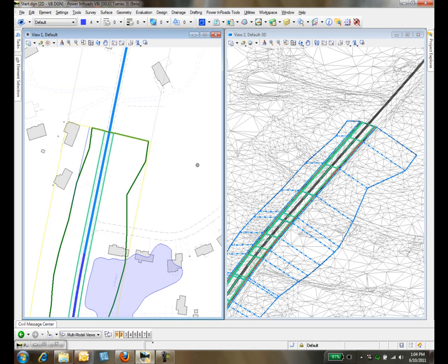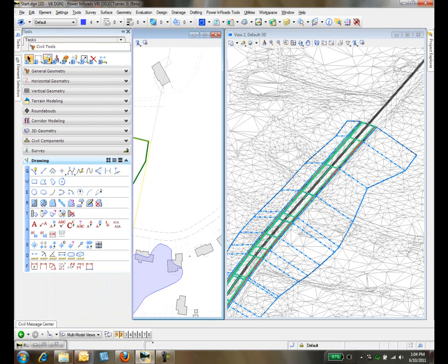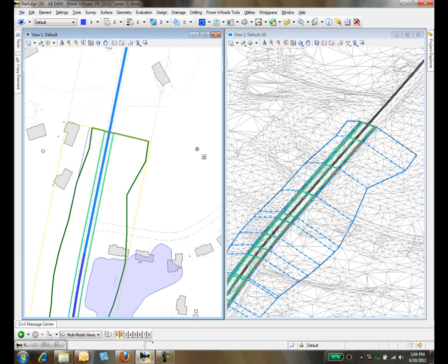But now here's the difference, okay? And this is very important to understand. What it just did when I did that is it basically stored a rule or a relationship behind the scenes that said, oh, you want me to stop this template drop at the end of that wall. Now the difference here is, let's say for example several weeks later I come back and I decide, you know what, we can't put that wall there.